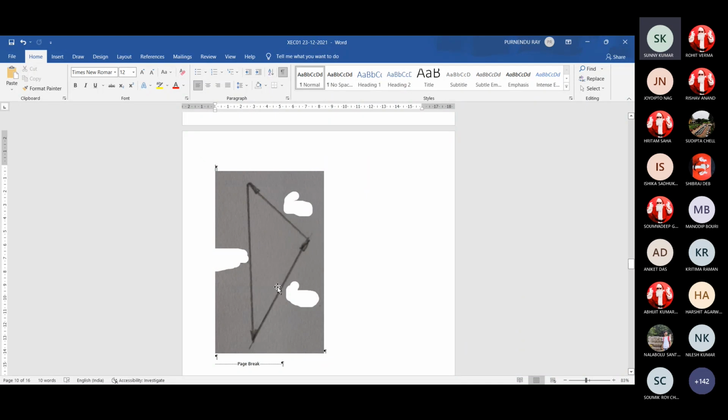It's not like the forward process, F1 plus F2 is the resultant R. It is some kind of backward process that represents the vector R in terms of any 2 arbitrary forces which can give us the resultant R. So this is one arbitrary force, this is another arbitrary force, but whatever they may be, they form a triangle. So vector F1, vector F2 for the first case, that is the resultant R. Here new vector F1 plus new vector F2 also gives the same resultant R.